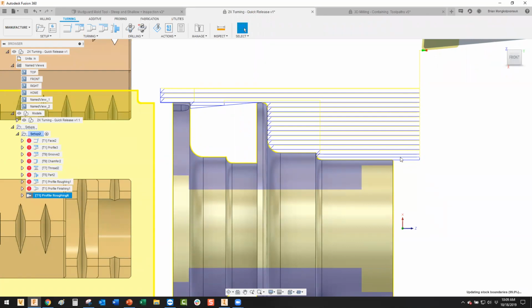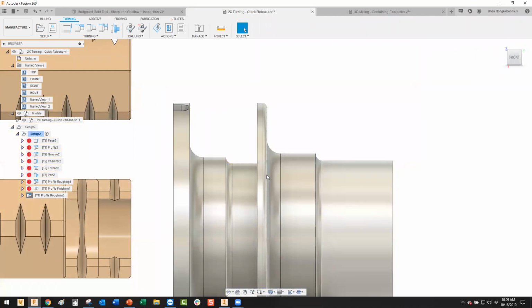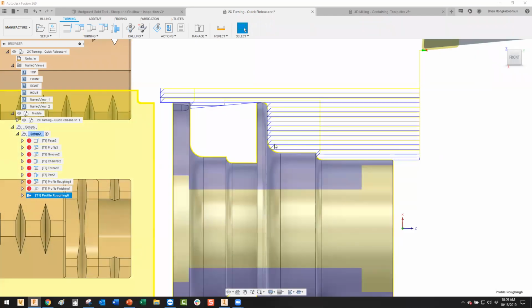If for whatever reason you measured it wrong or something like that, and you come in right away without that control, it has the possibility of giving you that weird burr or something in the beginning of that cut. So you just have that capability at the front, but as well as the back. I told it to extend just a little bit more in the back, so just to cut it a little bit cleaner there as well. So you have that capability with tangential extensions.